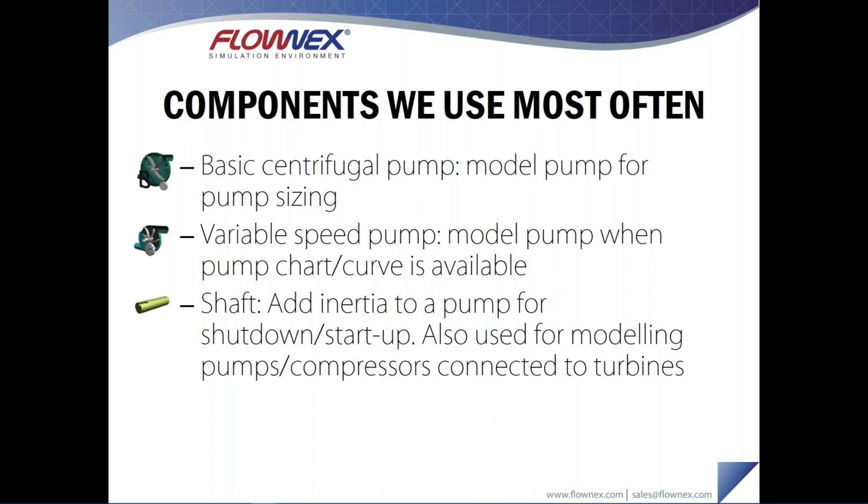Often with pumps, I'll use the shaft component as well to add inertia to the pump. The variable speed pump and basic centrifugal pump don't have inertia built into them inherently. To account for the inertia, you have to connect a shaft component. This is useful for doing startup or shutdown simulations. Perhaps there's a pump trip or a pump startup that you want to investigate. And the shaft component is also useful for connecting pumps to turbines in cases where you have a turbo-driven pump or a turbine driving a compressor, for example.